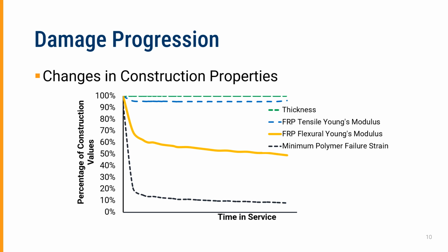However, if we're dealing with, for example, sodium hydroxide solution, we'll see a deeper or a steeper drop and a sharper drop. So it's chemically dependent. We're showing the 5th percentile for a group of chemicals that have been tested on polymers. And the reason we're doing that is to be conservative.